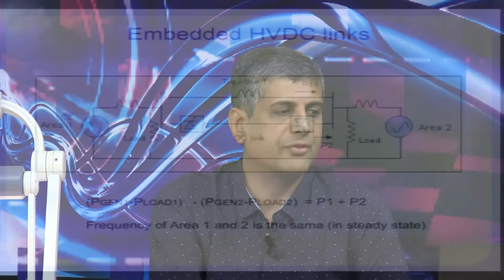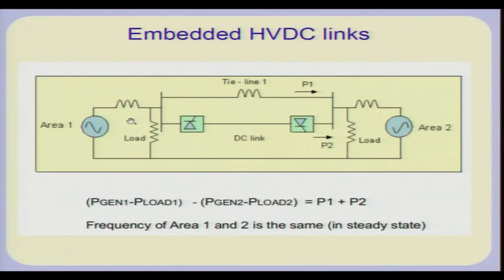The HVDC link here unfortunately or fortunately cannot do anything as far as controlling P1 plus P2, but it can control P2. Okay. So, it can in fact alleviate an overload in the parallel line, it could modulate power flow. In fact, you will have swings between the synchronous generators on this side and on this side. Okay. So, this kind of thing can happen in this situation.